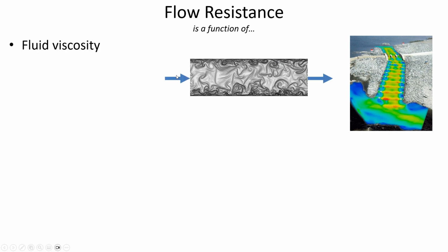That water that flows through a pipe is going to have a high velocity in the center of the pipe where it's furthest away from that stationary object that the water's in contact with. But around the edge, like think about a circular pipe, the water that's touching that pipe material is going to be moving at the same velocity as the pipe itself.